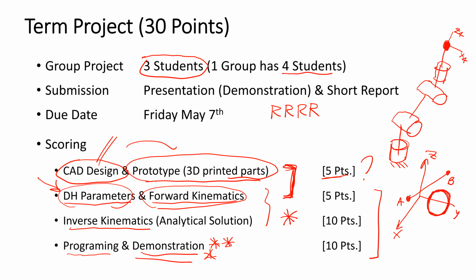If you want to move the end effector from point A to point B, the path of motion will have multiple endpoint positions. At each position, you need to decide the corresponding theta 1, theta 2, and theta 3, and of course, the theta 4, so that the end effector can move along the design trajectory.